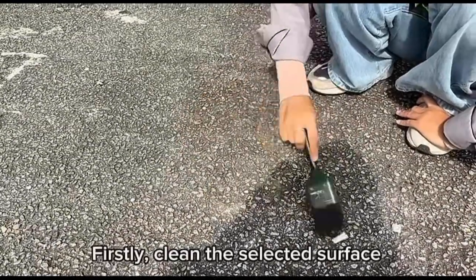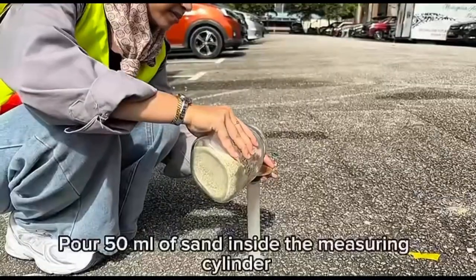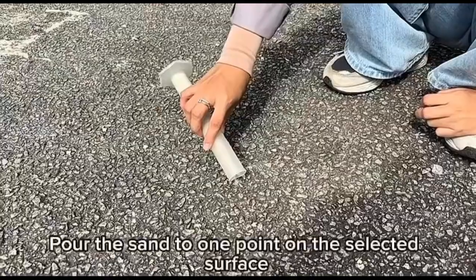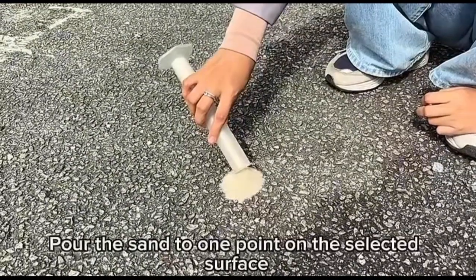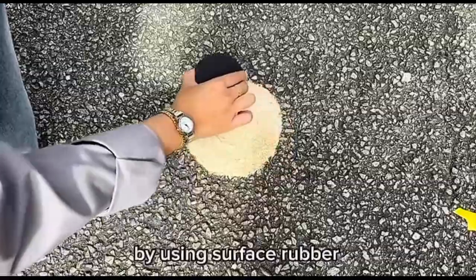Firstly, clean the selected surface, which is the rough surface, by using a brush. Pour 50 ml of sand inside the measuring cylinder by using the funnel. Pour the sand onto one point on the selected surface and disperse it in a circular motion by using the surface rub.